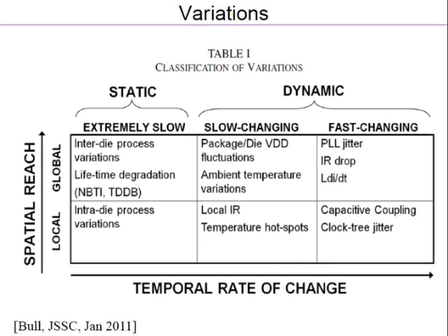At a time, tens or hundreds of AND gates will be fabricated. Intra-die, absolutely. So the question is, even though the gates are being fabricated at the same time, in the same process, in the same chip, will there be variation? Yes, the answer is there will be variation, because if you go back and look at the threshold voltage, what determines the threshold voltage? There are factors like the channel length, the doping concentration, etc.